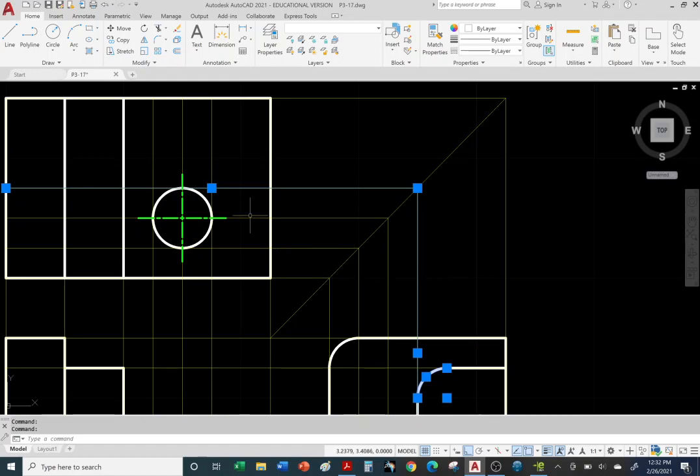All right, so let's go ahead and shorten this object line, right? We're going to match the yellow construction lines. So let's go ahead and shorten it. And there it is, okay? And now we can hit escape. So once again, we're matching it up with these two construction lines from the right side view. And there it is. And now we have to close this off.